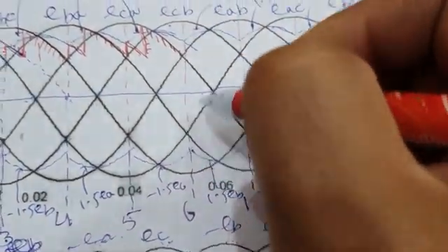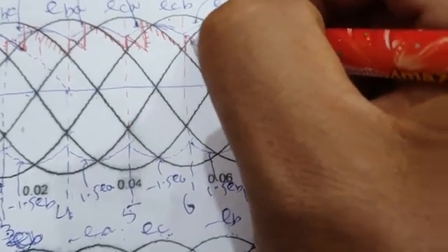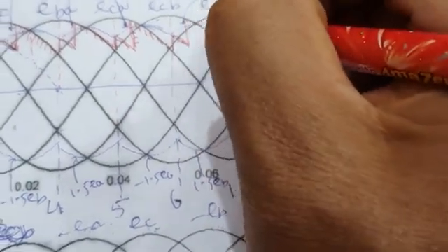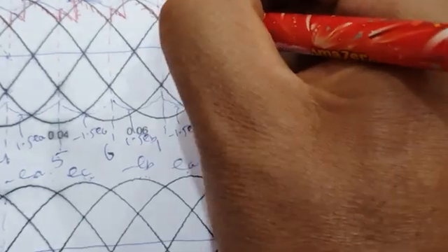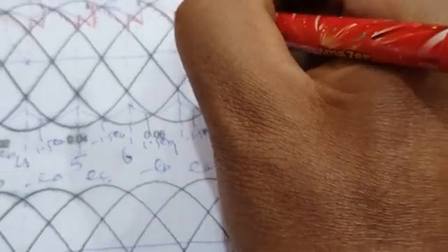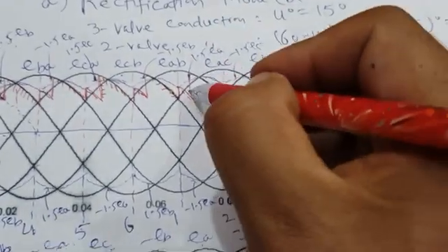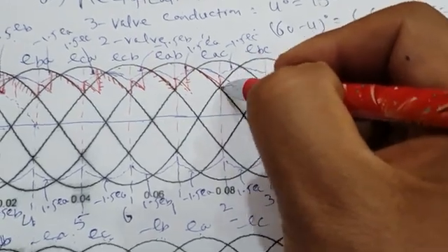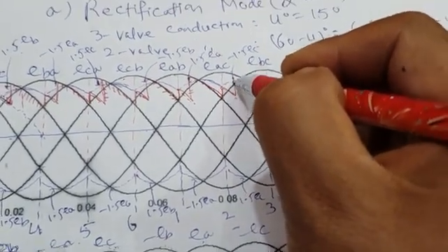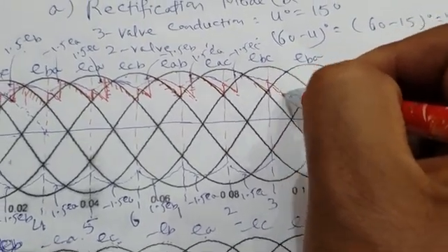Next firing happens here. So when the next firing happens, this is the 15 degree interval. This is the 45 degree interval. So continue like this. Okay, so 15 degrees, 45 degrees, like this. Follow this pattern. Then you can see this is 15 degrees followed by 45 degrees. That's it. After that 3 fires again.